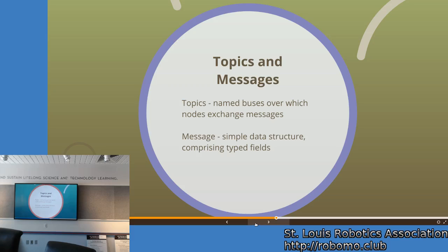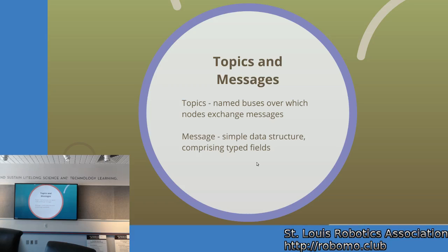That's actually changing in the new version of ROS, ROS 2. They're switching to a message queue system. I think they're using 0MQ. So I think that'll allow multicasting, and they won't directly connect. Well, actually they might, so I'm not going to get into that. They also offer guaranteed delivery if they go to that. If a node goes down and there's messages, it'll wait till the node comes back up and then send the messages to it.